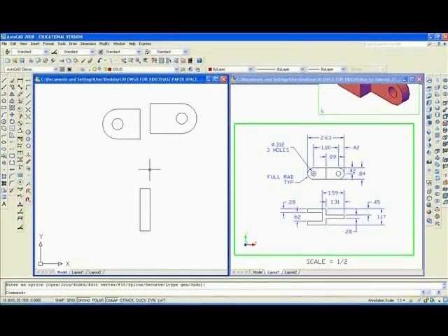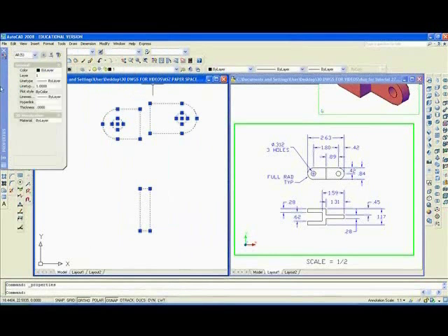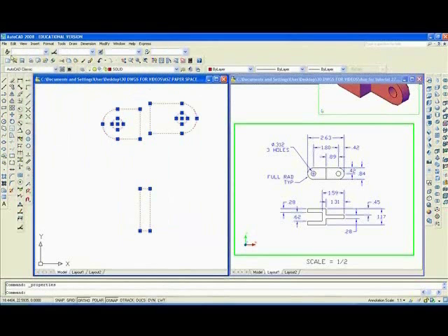Also, going to make a polyline here, join, J, enter, and then we're going to make the whole thing, put it on layer solid. And move into southeast isometric view.